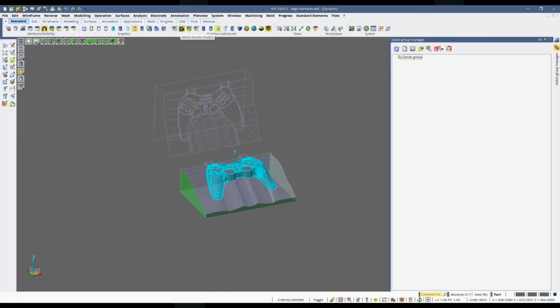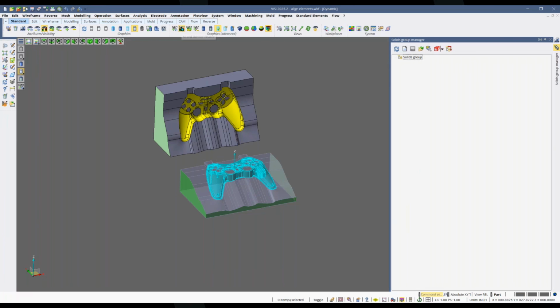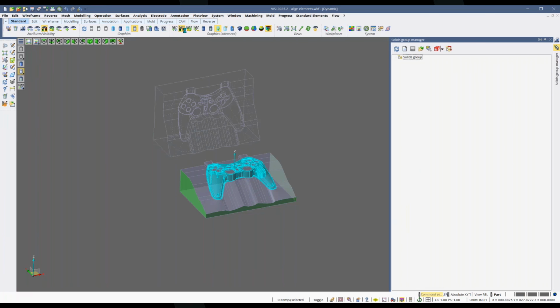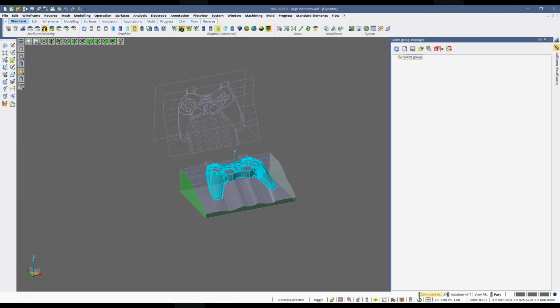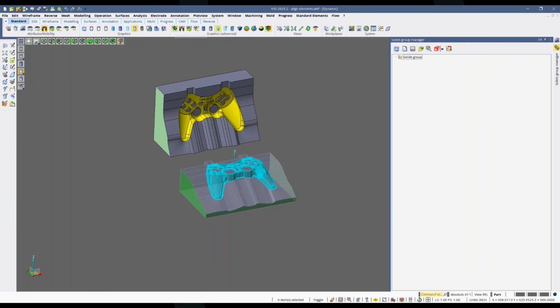So once you enable the mixed render, you can hit that button, the stoplight, just like with the eyeballs. So the command is called mixed render enable. It'll turn it on and off. But if you've selected one element, it's easiest to just turn it off and reselect an element to reset it. And just use that first icon versus the last icon, which is subtract additional for the mixed render.